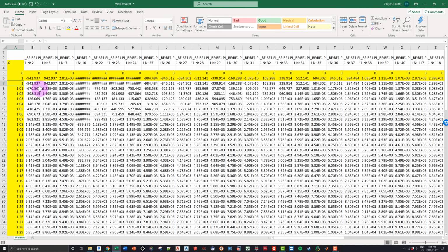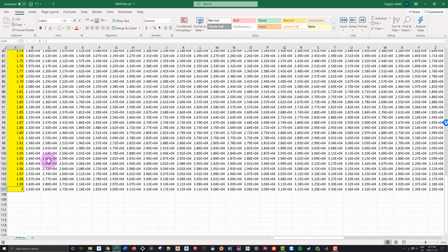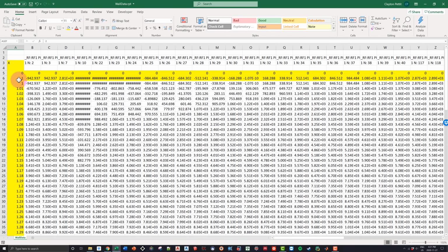Now remember, our lateral load occurred in our second step, so our timestamp is going to be from 1 all the way until 2 down here. This makes sense to us, of course, because we specifically wanted this load to be applied in 1% increments. This is why it goes from 1 to 1.01 to 1.02 to 1.03, etc., all the way through. So this is the data that we actually want.